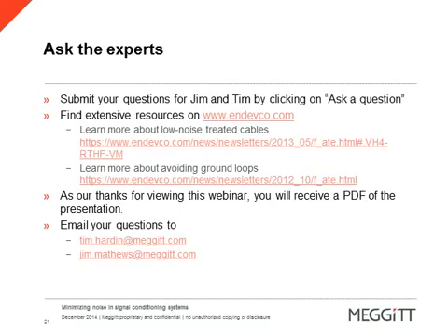Yes, I agree, Jim. With proper grounding technique, if the sensor is isolated, as stated, using an isolated mounting stud, then the amplifier needs to be grounded. So that would be in the grounded mode and not in the isolated mode. You would not want to pass that signal through the 2775B and then on to your data acquisition system, even though it may have an ISO or grounded setting on it. You would want to ground the 2775B.